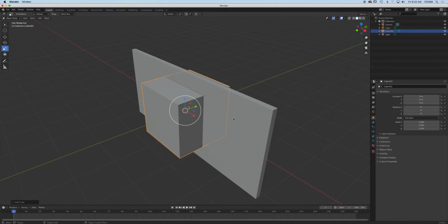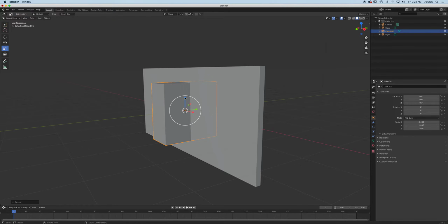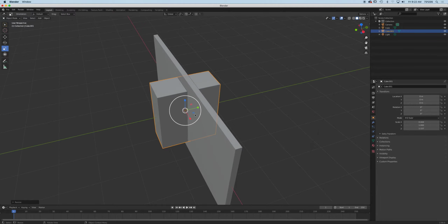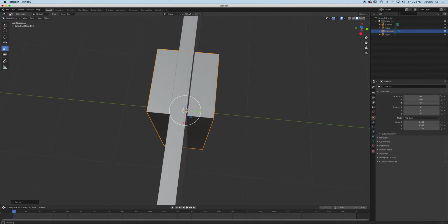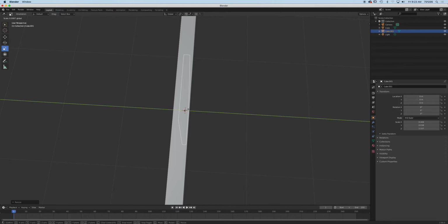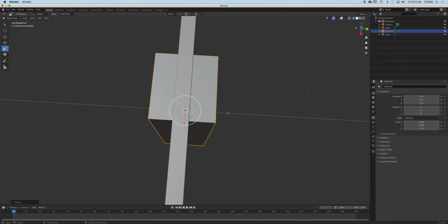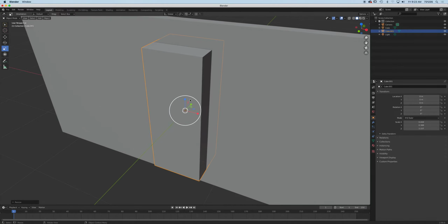All right. So I'm going to, let's say these are those kind of tall wall-to-wall windows, okay? The only requirement here is this is your cookie cutter. You want it thicker than the wall, right? If this is slimmer than the wall, then you basically made a hole for the rats, right? There's a rat in the middle of the wall. You can't see it, all right? So make sure it's thicker than what it's actually cutting, right?